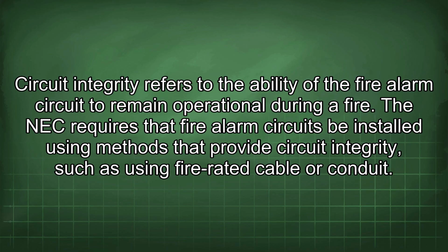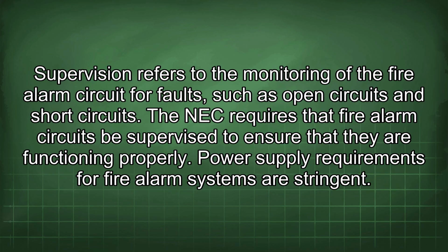The NEC requires that fire alarm circuits be installed using methods that provide circuit integrity, such as using fire-rated cable or conduit. Supervision refers to the monitoring of the fire alarm circuit for faults, such as open circuits and short circuits. The NEC requires that fire alarm circuits be supervised to ensure that they are functioning properly.